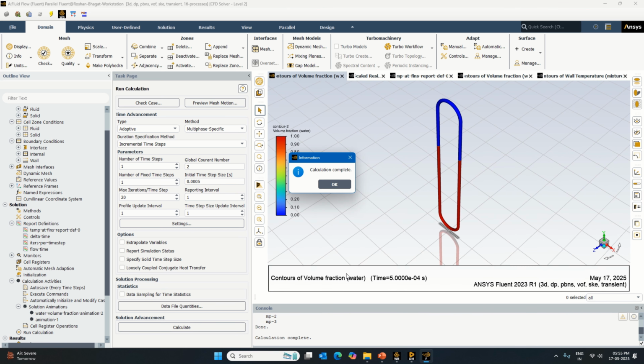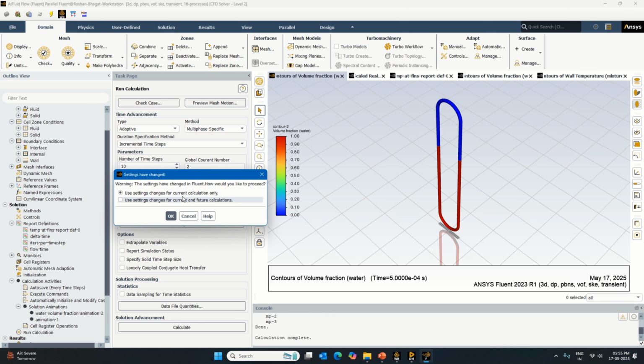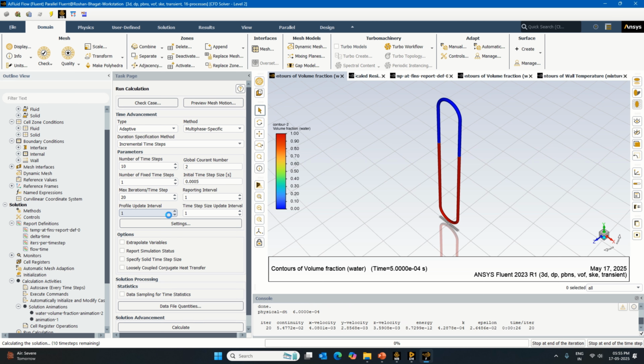If you take a very big time step size, there are chances of the floating point exception error, and that's why it is very important that when you run the simulation, you run it for a smaller time step size. Again, whatever mesh size we have selected, based upon that mesh size the time requirement will be more or less. We purposefully took the mesh size comparatively on the lower side, below 10 lakh nodes and elements. So if we are on the lower side, the time requirement will be less. But if we take a very fine mesh, the time requirement will be more.